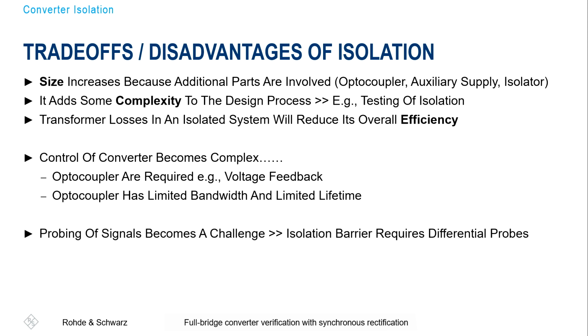And when we come to measurements, because you want to verify your design, that is also a challenge. It's at least more complicated and more complex, because due to this isolation, you must not violate your isolation barrier, and therefore you need a really good selection of probing. And the key word here is the differential probes. We come to that in a few minutes.